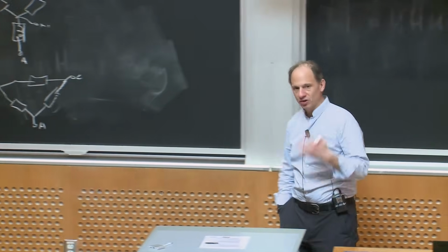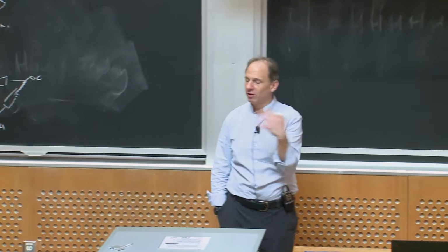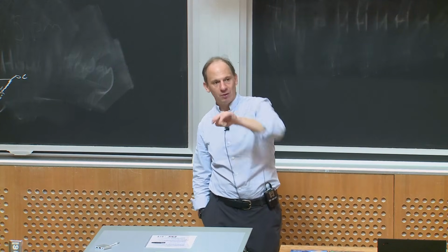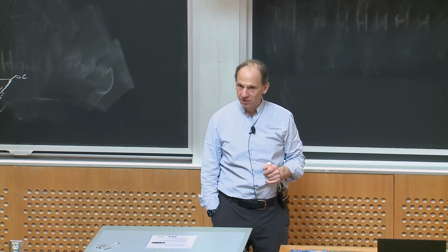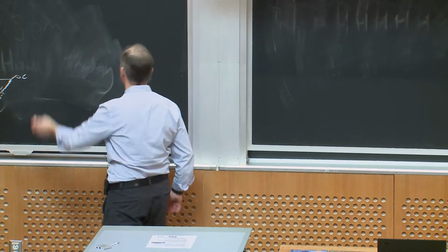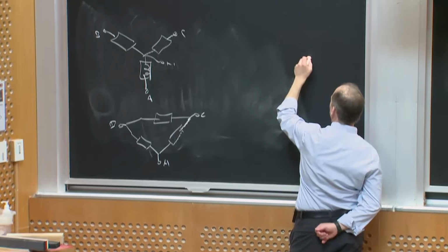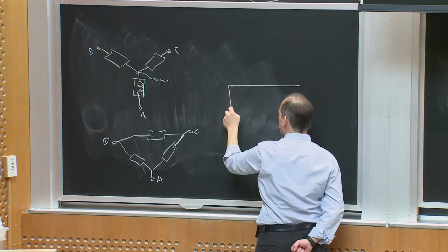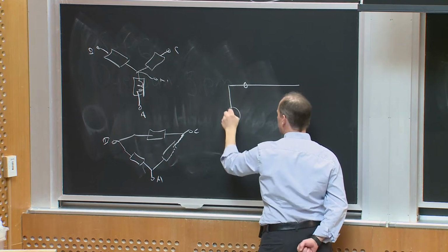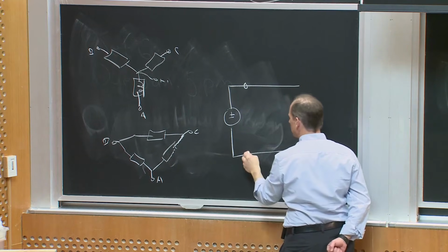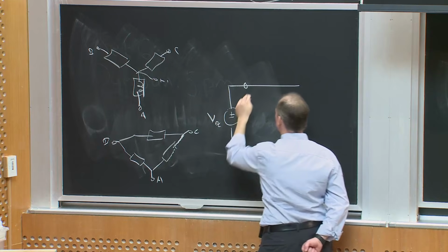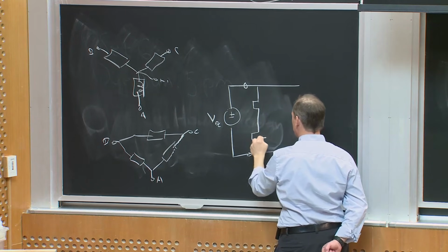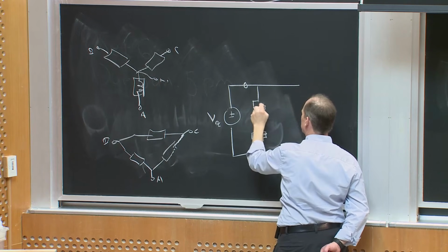It's very much the structure that we saw with the three-phase bridge rectifier. Instead of having diodes, however, I will have active switches, okay? So maybe I would come up and build something like this. I'll have my DC bus come in, so I'll have 2 terminals, VDC, right? I will have a first bridge leg like this, and let me make sure and show the diodes again.